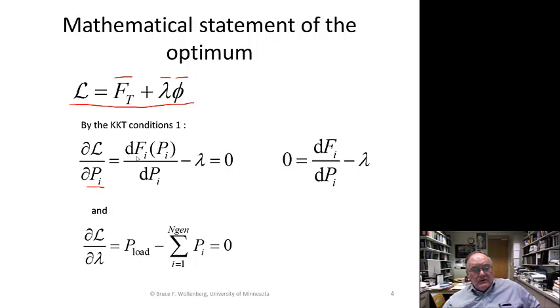Remember that you'll see the term incremental cost sometimes in books and publications on power systems. Technically, the economists that we work with say that that's a marginal cost. It's the derivative of the cost function at generator i, so it's dfi of pi with respect to pi.